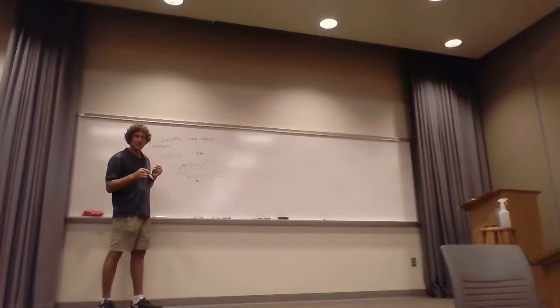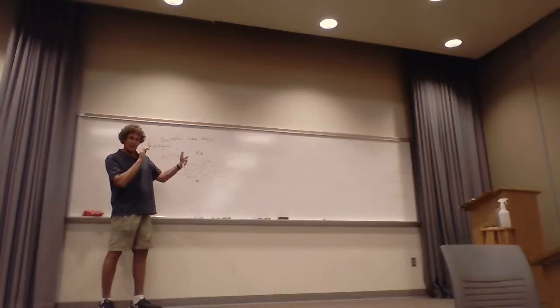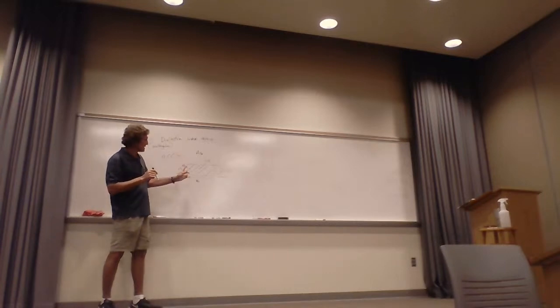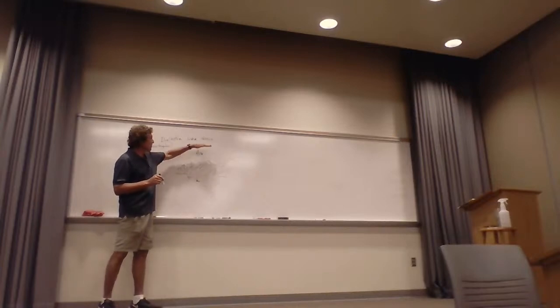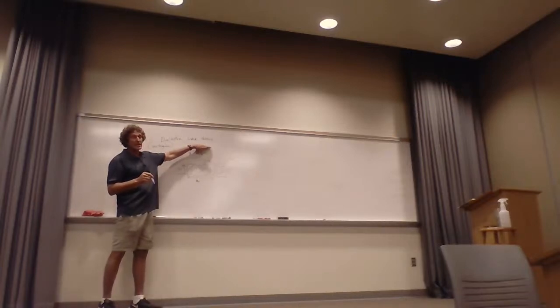Now, we use the tangent electric field equal to zero to get the boundary conditions and then solve for the allowable solutions for rectangular guides. Y'all remember that, right? We did that. Here, you don't have that. The way you have to solve it, and I want to try to explain this, inside the guide, the sine and cosine variation in the horizontal and vertical component will be the same, as well as the e to the plus or minus j beta z times z propagation term. But out here, there will also be an electric and magnetic field possible. Just bear with me, guys.